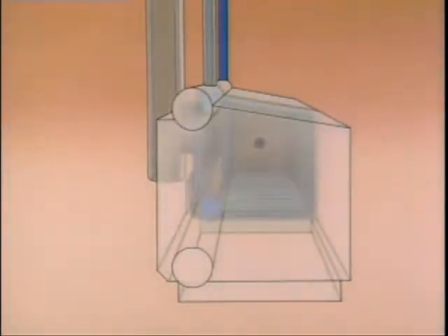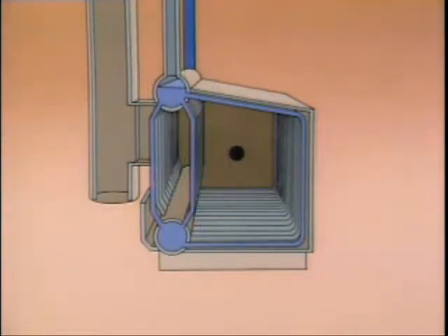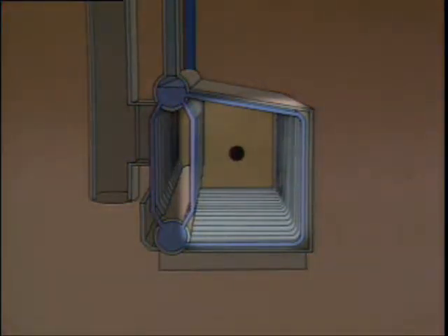This type of boiler is called a water tube boiler, but the heat transfer principles at work apply to just about all boilers. The boiler has a series of tubes and two drums which distribute water to the tubes. The tubes form a wall around the combustion area. This is the area where heat is generated.